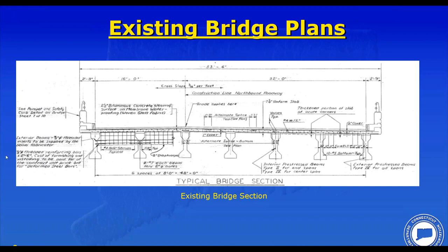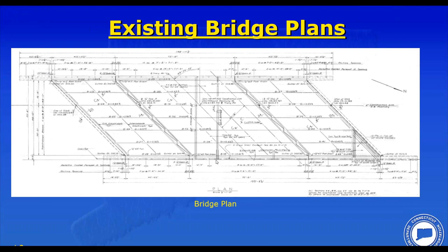The bridge joints are problematic. This is where we're going to see problems on this bridge. Because of the AASHTO girders, the original designer decided to zigzag the joints at the end of the bridge, a very unusual joint configuration brought on by the skew of the structure. So you have this zigzag joint, and you can just imagine, how the heck can I build a bridge joint that won't leak with zigzag joints? And the answer is you can't, and they leak, and that's a problem.